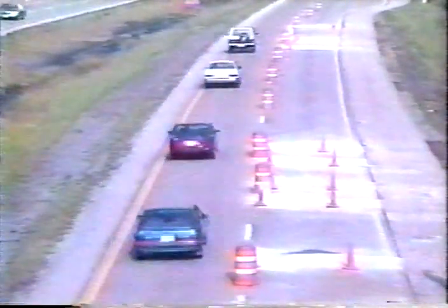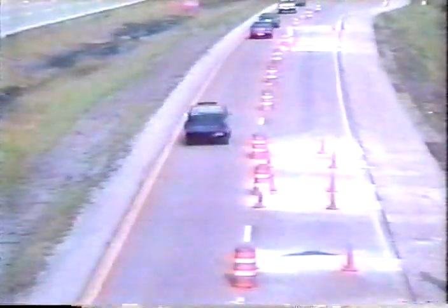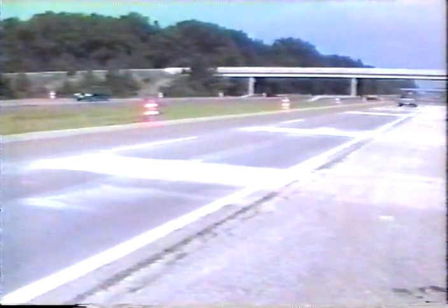When evaluating traffic opening times, it is recommended that the lowest or coolest thermocouple be used, since critical load-induced flexural tensile stresses generally occur at the bottom of slabs. However, when used as a quality assurance tool, maturity is usually calculated using the overall average slab temperature.